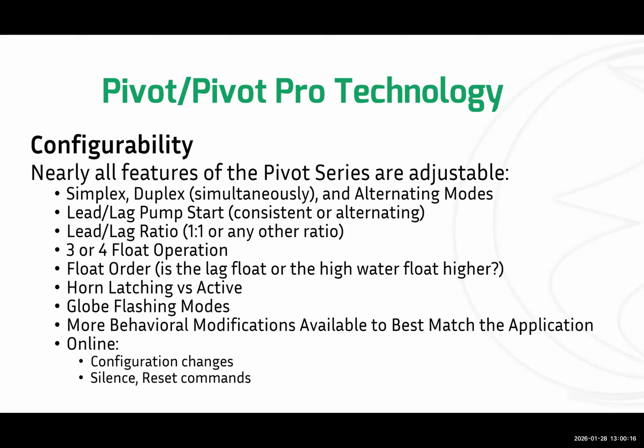Let's say that a pump overheats and you have a thermal alarm. Well, you obviously want that alarm to scream, but eventually that pump's going to cool down and it will come back into service. When that happens, if you have it set as horn active, it will stop screaming when that pump comes back into service. Now, the panel will still be in alarm mode, but the horn itself will stop screaming. The beacon will still be lit to indicate that there was a problem.